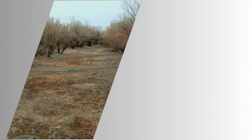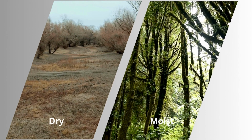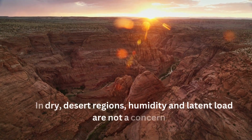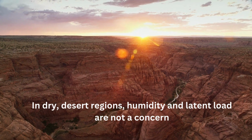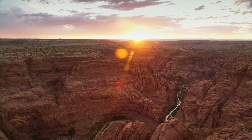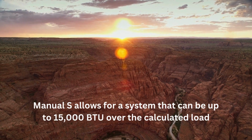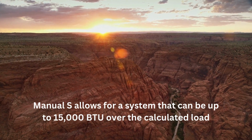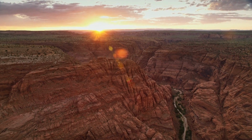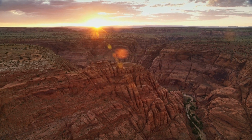Another aspect of the climate zones to mention again is the difference between the dry and moist regions. In the dry desert regions of the western U.S., such as Arizona, humidity and latent load are not issues. This is why for equipment sizing, the guideline of Manual S allows for a system that can be up to 15,000 BTUs over the calculated load. This means it's okay for a system in a dry climate to be a little bit oversized because you don't have to worry so much about removing moisture from the air.